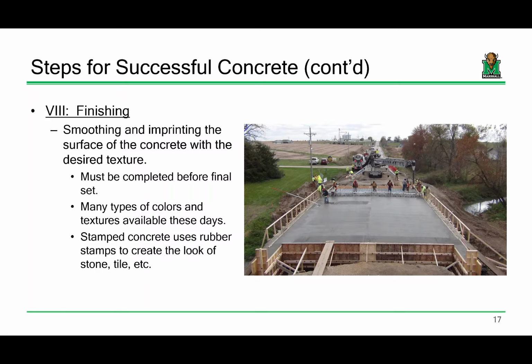Now what they're doing is the act of finishing the bridge, okay? So finishing the bridge involves ensuring that the surface is smooth once the concrete has consolidated and cured. Now, I say smooth, but smooth is actually not the correct goal at the end of the finishing operation. We don't necessarily want a smooth surface on top, we want a desired surface on top, okay? What do I mean by that?